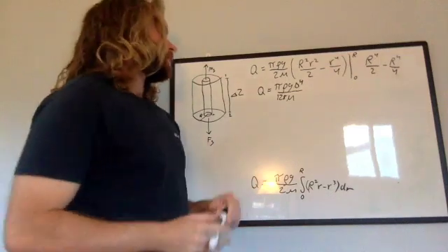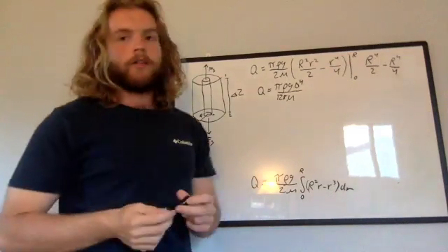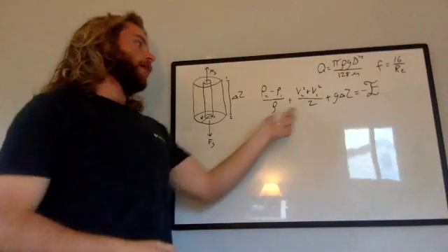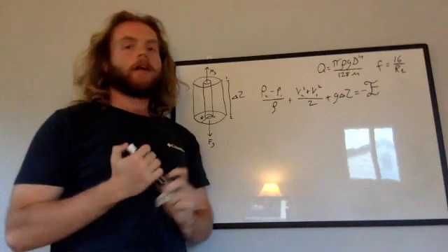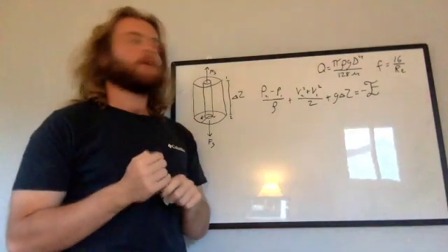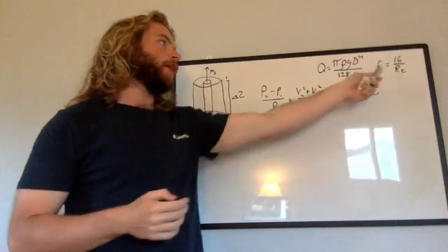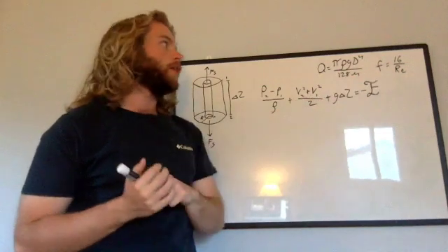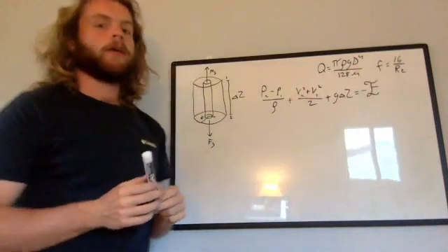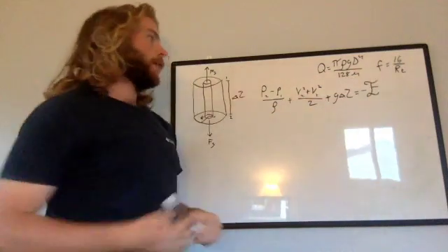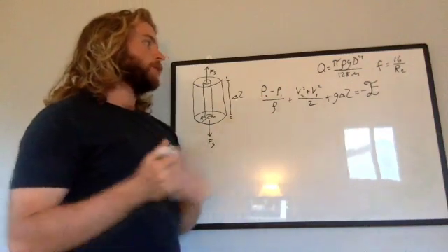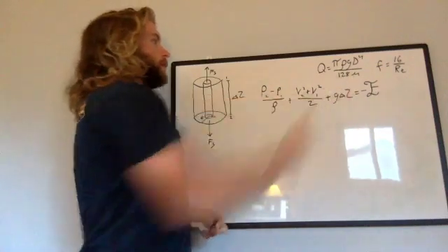And we're going to go ahead and get into our Bernoulli's equation. Okay, so I've gone ahead and written down the Bernoulli's equation right here, and the reason I have done this is because the end goal for this problem is to show that the fanning friction factor right here is going to be equal to 16 over the Reynolds number for this laminar flow. In order to get that, we're going to have to bring in this Bernoulli's equation, so we'll take a look at this now.